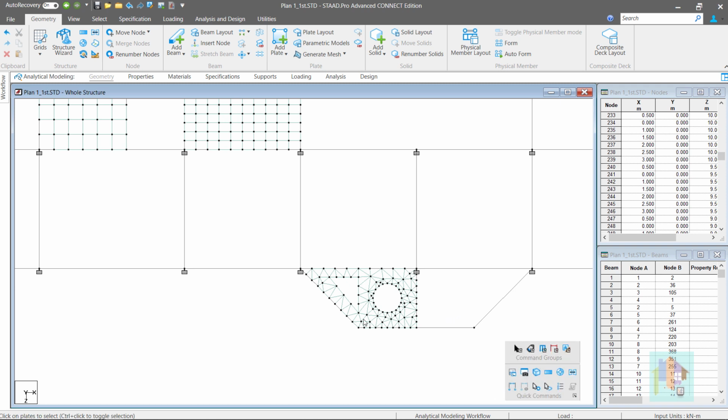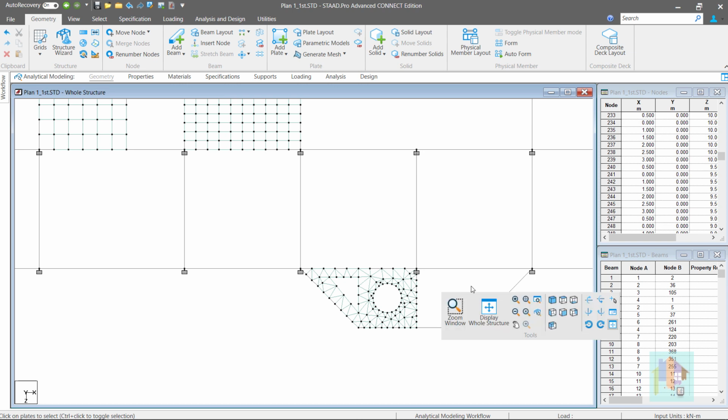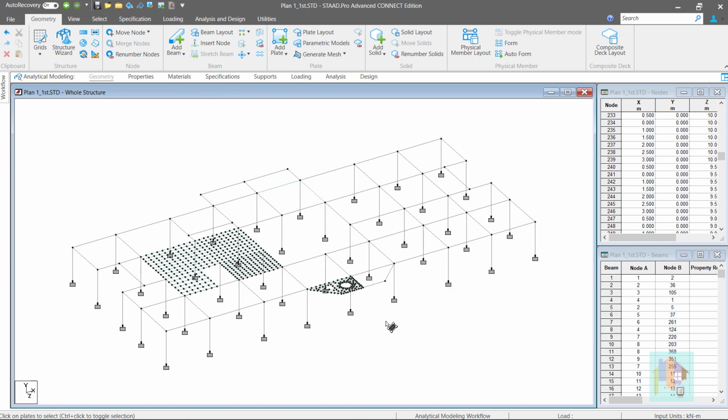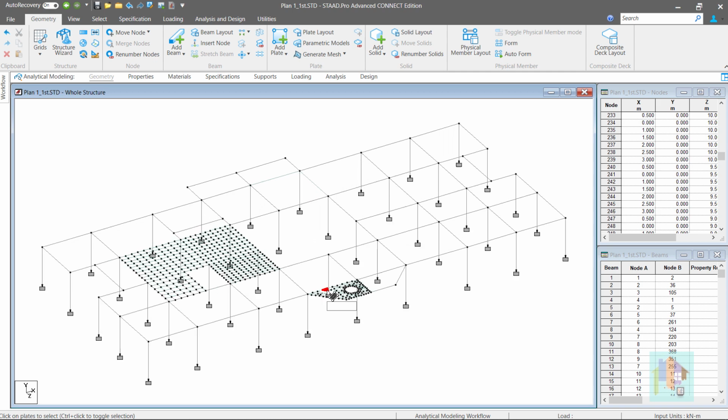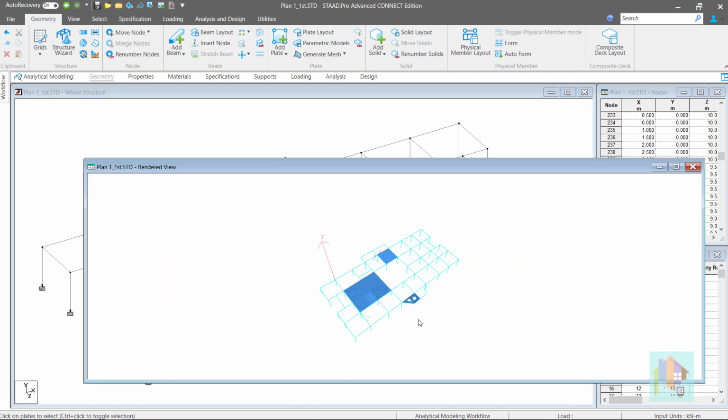And you can notice the meshing is accurate near the holes. This plate mesh looks fine, and within this boundary, there is no issue with plate connectivity. But you need to mesh other panels cautiously so that the edge divisions match between different panels. This method of mesh generation is widely used to generate a plate mesh for slab or mat foundation or any FEM model like silo or retaining wall.